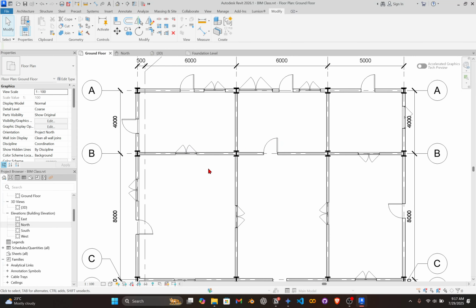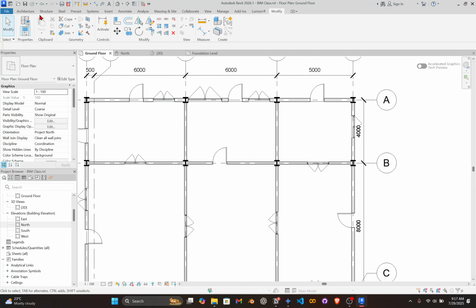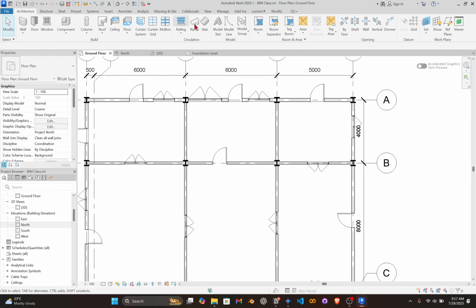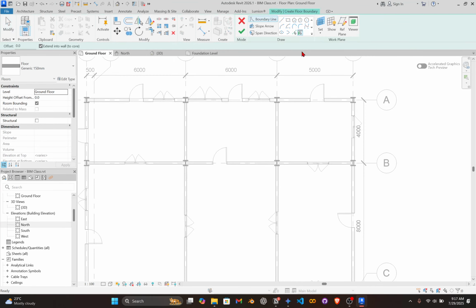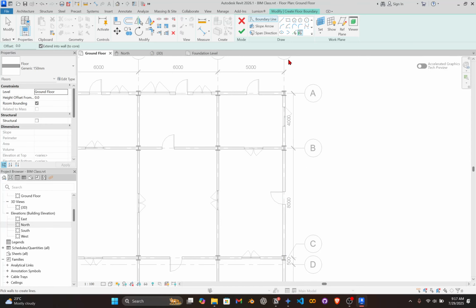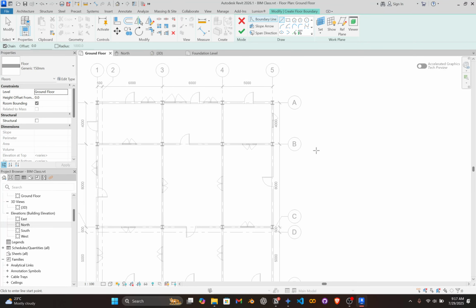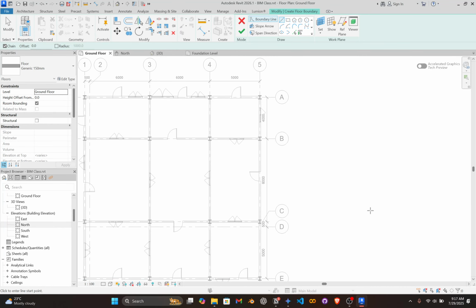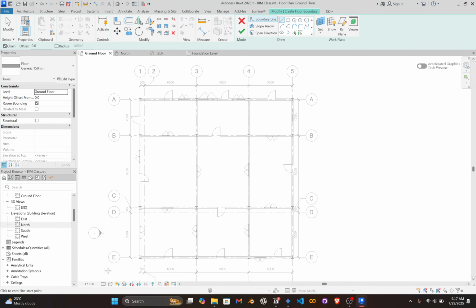Now, the very last thing I would like to point out, all right, is that when, for example, you are creating your floors, if I go to floor creation, Revit always provides a hint depending on the tool that you are using. So if I go to the line tool, if you look at this side of the screen, when I move my pointer, it might change. But yes, so you see, click to enter line start point. Revit gives you a hint as to how to use the particular tool. If I click once, see that it now changes to enter line end point, and I can just do that.